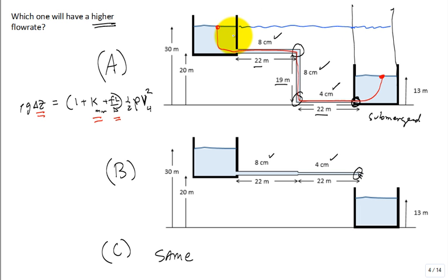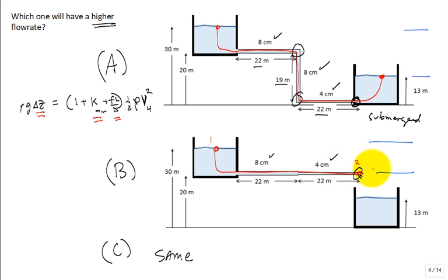Is there going to be any flow? No, there isn't going to be any flow. True? All right. So what drives the flow is 7 extra meters, compared to this system right here. Here's Bernoulli, and it goes there from 1 to 2. And so what was the delta Z for this case? 10 meters. What was the delta Z that drives the flow in this case?